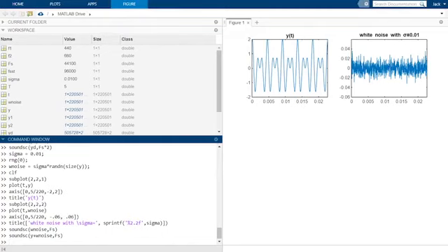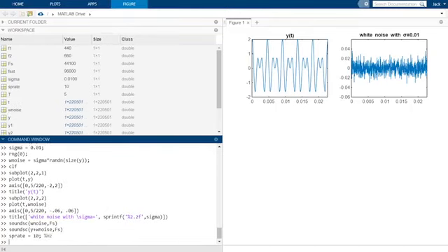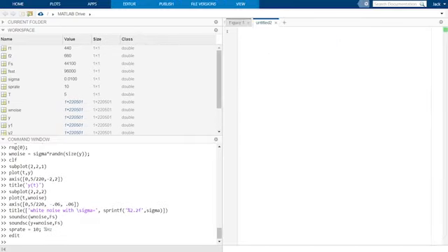First, we choose how much salt and pepper we want. I'm going to choose a frequency of 10 hertz for about 10 crackles per second. Then we can write code to create our salt and pepper noise. Let's put it in a function. A function will take as inputs the salt and pepper rate, our time vector t, and sampling rate fs.